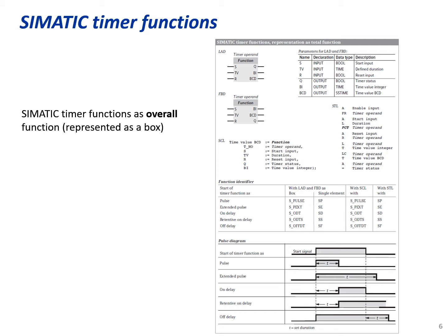And the off delay timer, as it is clear from the name, the start signal should go from on to off. And once that happens, the output doesn't go from on to off immediately, but it will go to off after a delay of t seconds. All of these definitions are the same for Codesys. You could find on delay, off delay, and retentive on delay timer also in Codesys.